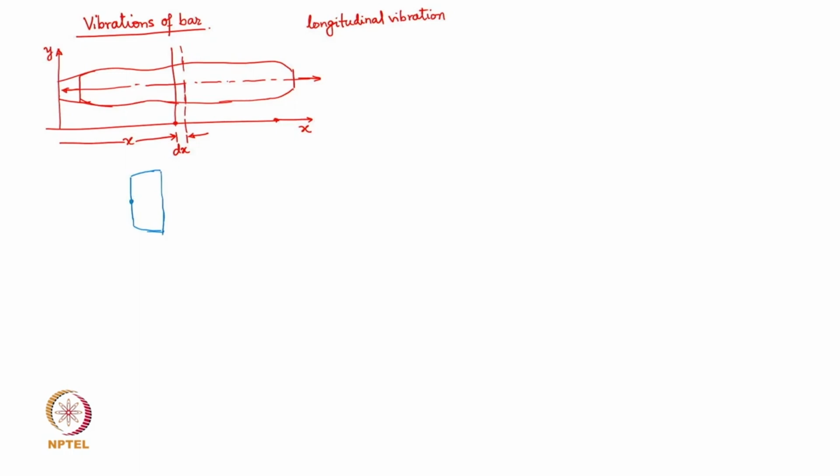Now, under the continuous action of all the forces which are set up in the bar, we find that the bar is under equilibrium under the action of these internal forces which are set up at position x. Okay, the original distance here is dx, as we have taken a small infinitesimally small element here out of the total bar of this continuum, and let this get stretched under the action of these forces.